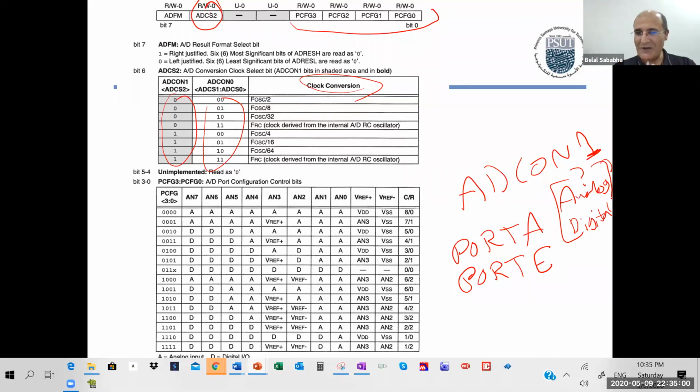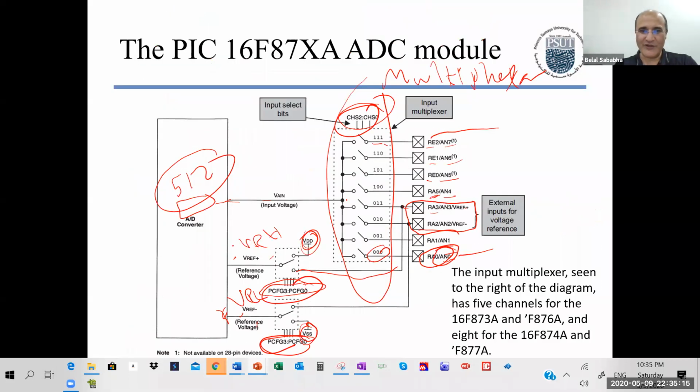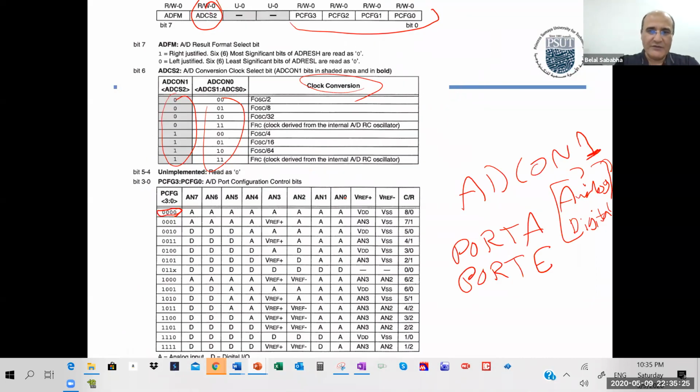The default, if you remember, when I was using this microcontroller I said this last time, I never use port A. I never used port A because the default of these bits is usually zeros. And look at this. Port A, here is port A. Port A0 is AN0, AN1, AN2, AN3 and AN4. From 0 to 4, these are port A. Their default is analog.